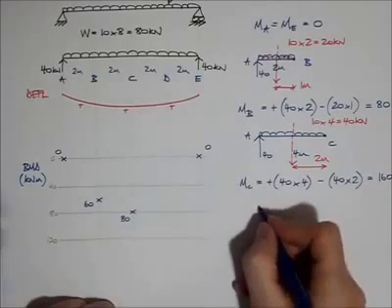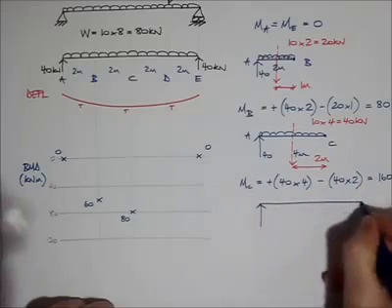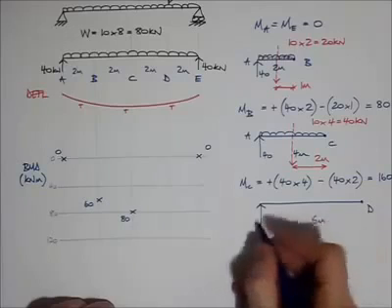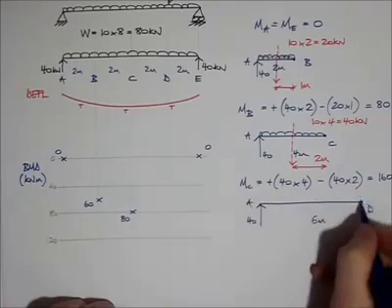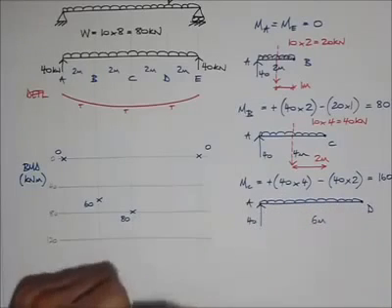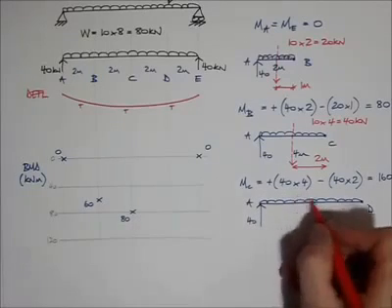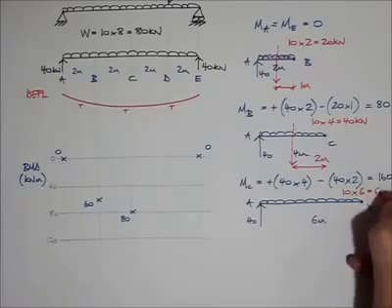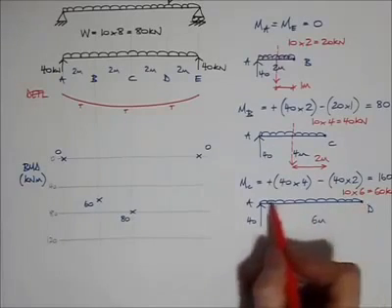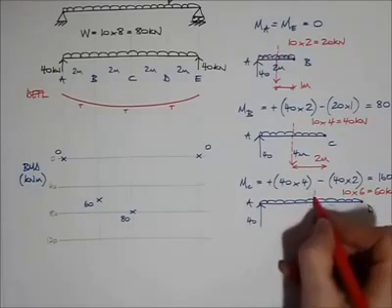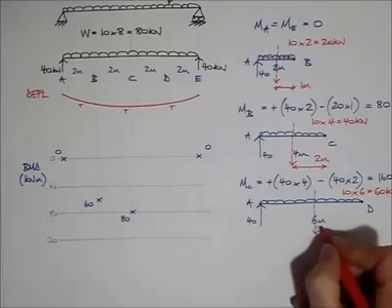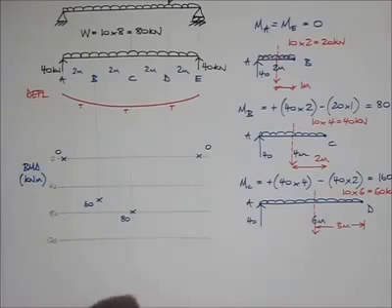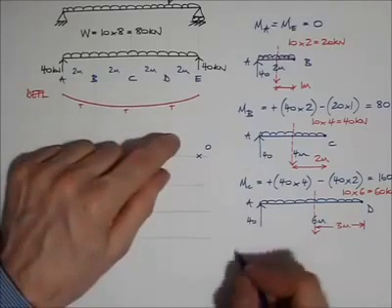So I'm going to draw out the free body diagram at point D. That's 6 meters. Got 40 kilonewtons there at A. And I have the UDL, which is 10 kilonewtons a meter over a length of 6 meters, so it all adds up to 60 kilonewtons, and it acts at its centre, so the centre of the UDL, I reckon that is 3 meters from point D. Great. So now let's take moments about point D.